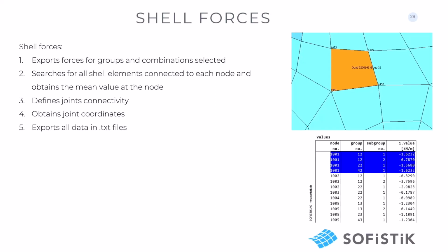So we have to model with shell, and that's a very bad thing because it's very complex to understand the behavior of shell with respect to a beam. Beam is moment, axial force, very easy. With shell, you have a very complex thing, and CLT has more complexity. I will show you in a sec.